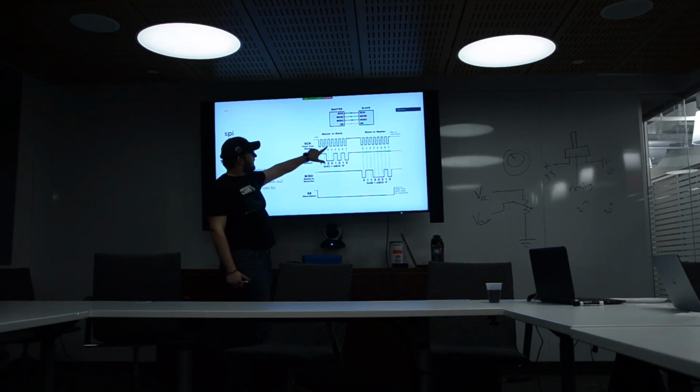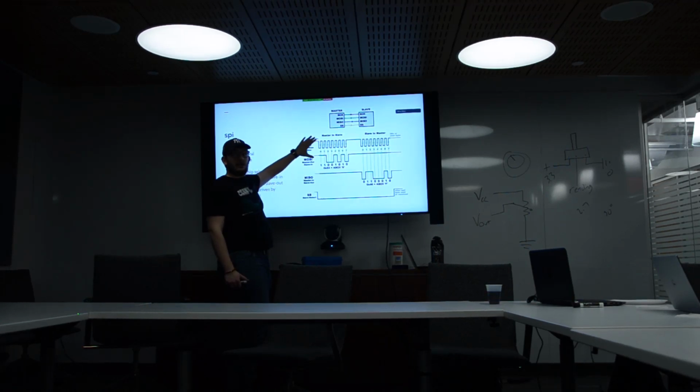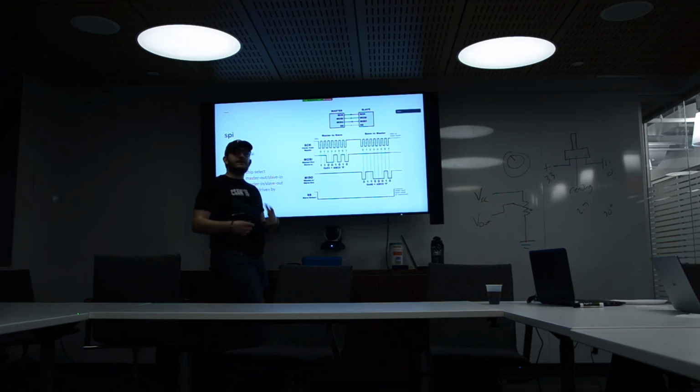And when it's low and the clock goes high, we call that a 0. So by taking advantage of just being able to pull this line low and high in relation to where the clock cycles are, we get binary data. We get purely digital data that the processor can understand without having to do any other conversion, because it just stores it in a buffer internally, puts it all together, and then boom, that's the value. That's the beauty of using a serial port, because all the data is already digital.